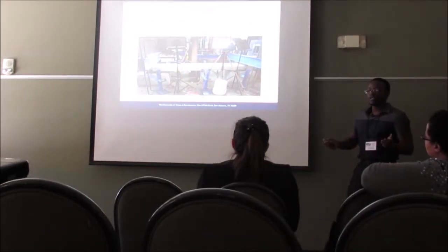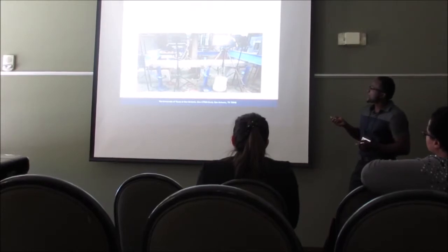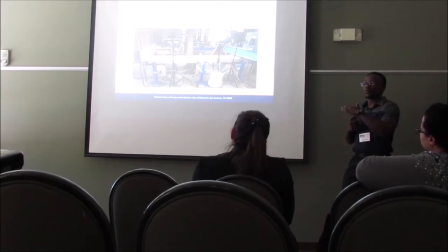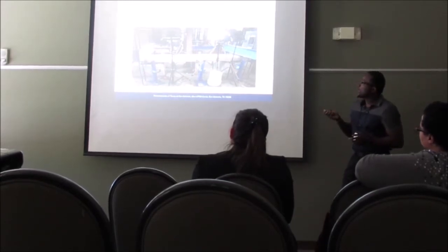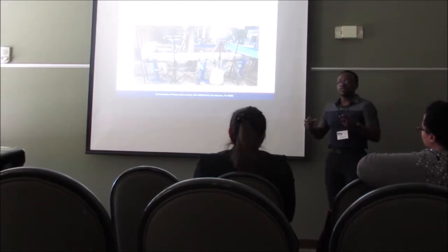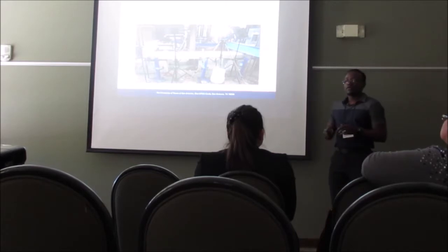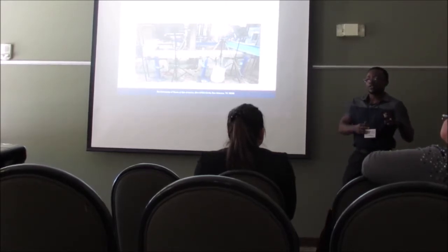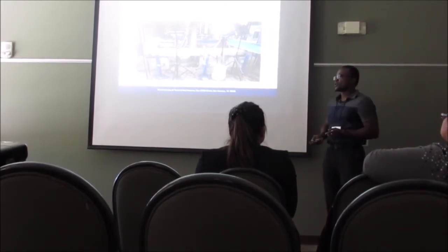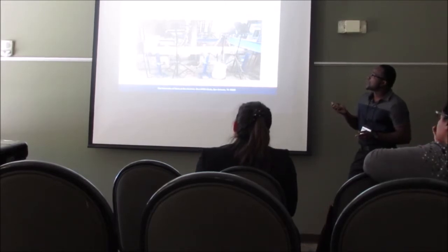So for our test, we use a monotonic tension test. And by monotonic, what I mean is, this is one of our specimens, and right at the center here, we have a load cell, and we load them at one point in the center, and we measure the deformation using strain gauges and different digital image correlation systems. And we tested a total of 8 concrete slabs. 4 were reinforced with the regular deformed bars that are currently used in construction, and 4 were reinforced with the spiral bars that use 2 different diameters, the 5/16 inches and the 3/8 inches.